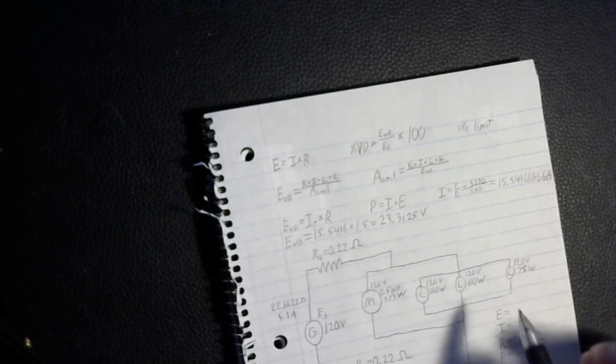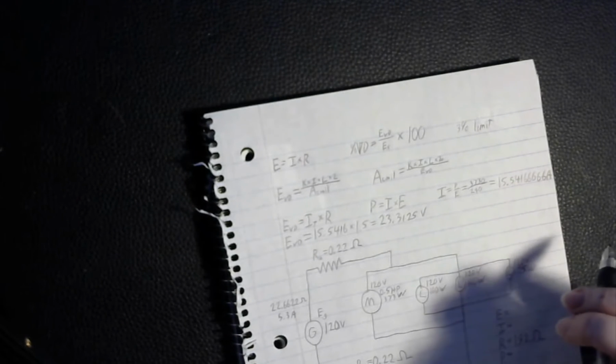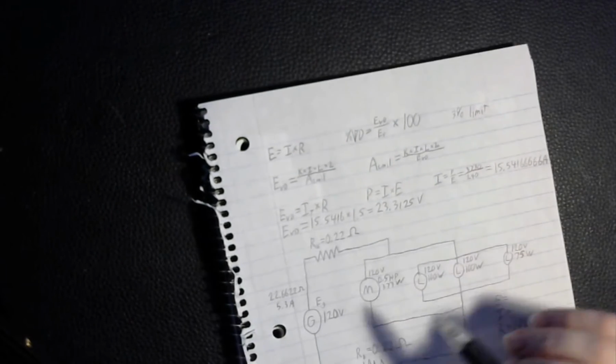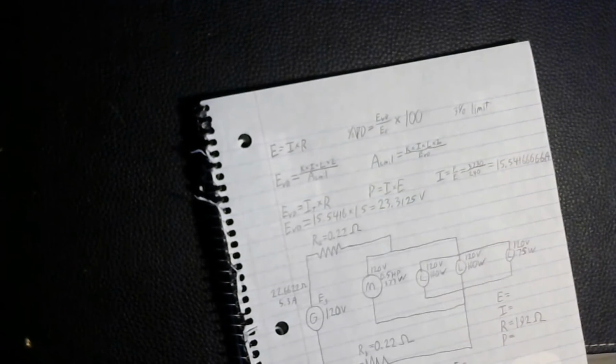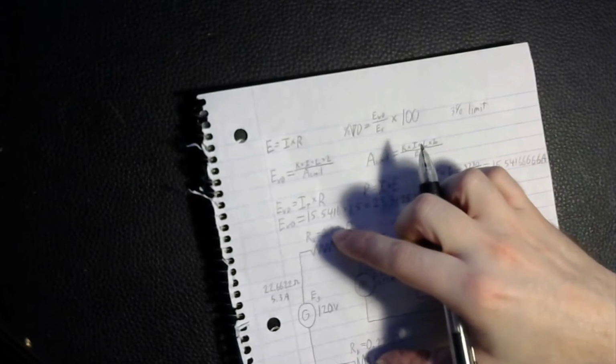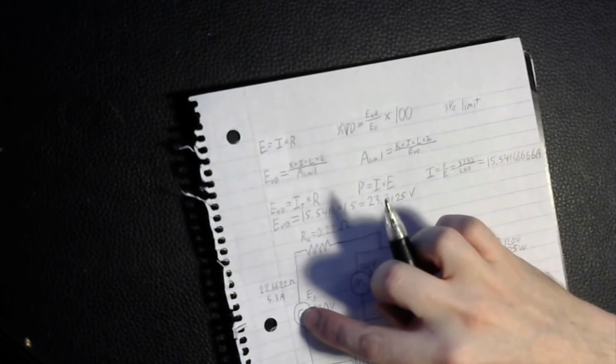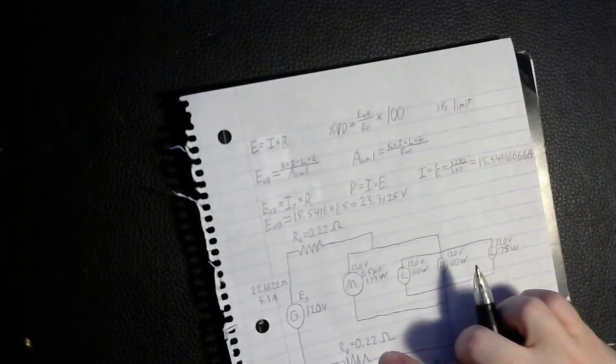It's effectively the same as getting your voltage drop for anything in a series circuit. So we're just looking for the voltage drop across just the wires. And that's on both ends. So do you add those two together? Yeah, you'd add these two together. You'd want to add the resistance of all the wire that's running between your source and your load. So in this case, we've got 0.22 ohms here, 0.22 ohms here, so it's going to be 0.44 ohms.